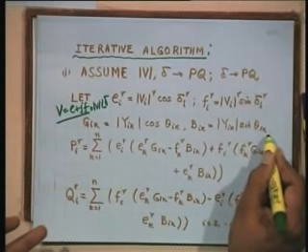If it is not, then you are solving an ill conditioned system where R becomes comparable to X, and still you can solve load flow because certain systems are ill conditioned, but the Newton-Raphson method will always give you an answer even if it is ill conditioned system, which is not guaranteed with Gauss-Seidel method. So, Bik susceptance is Yik sine theta ik.